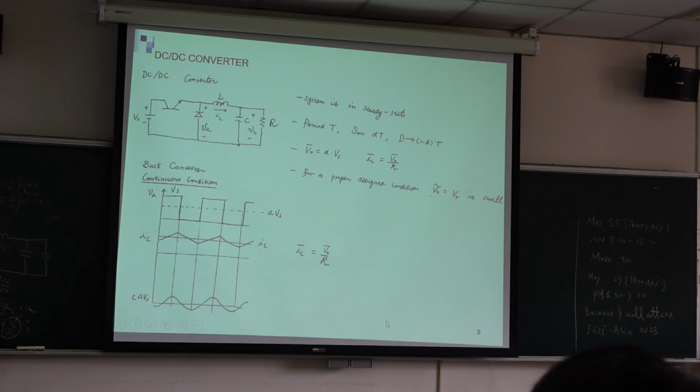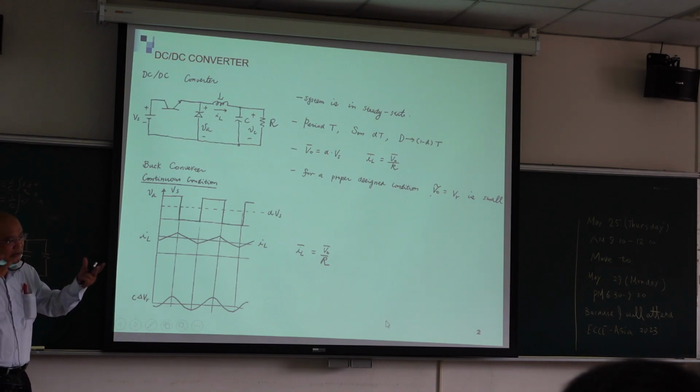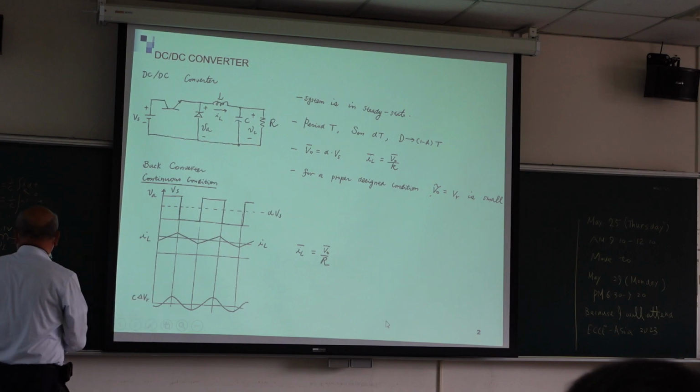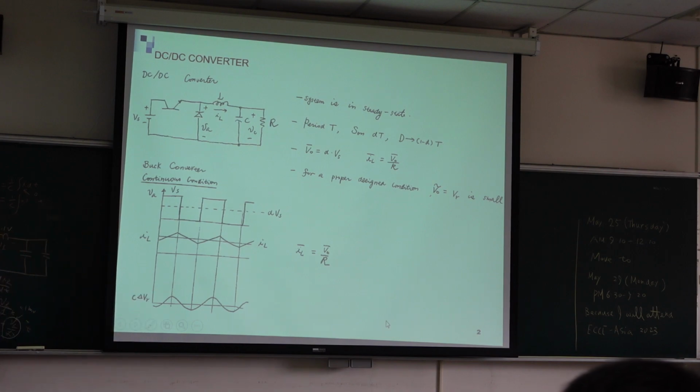When the time is infinity, what is this value? Infinity. So even if you have a very small voltage across here, after infinite time, the current becomes infinity. Is it possible to have infinite current? Impossible. So what is the conclusion? In steady state, the voltage across the inductor should be equal to 0, and the current of the capacitor should be equal to 0.